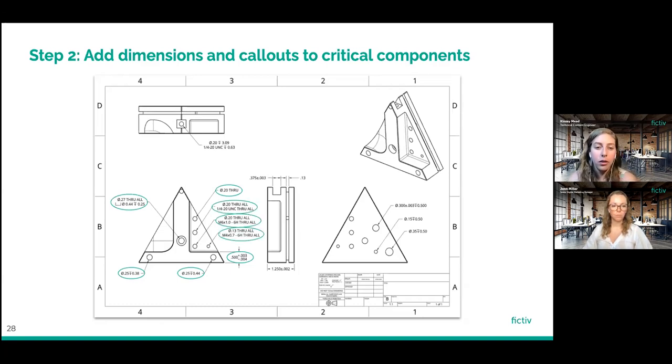And then we have these 3 through holes, which are also tapped all the way through, as you can see from the note. And it's important to pay attention to the threading on these because we have another 1/4-20 tap, but then we also have an M6 by 1.0 and M4 by 0.7. So when you see that M6, for instance, that's going to be a metric tap, which means the M6 part alerts you to the diameter of the hole, and then 1.0 or 0.7 is going to be the length of a single thread.